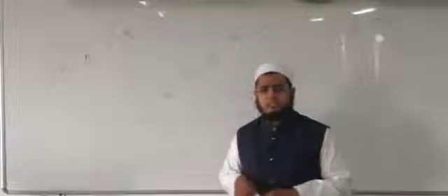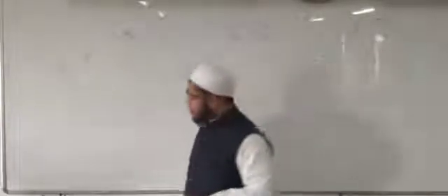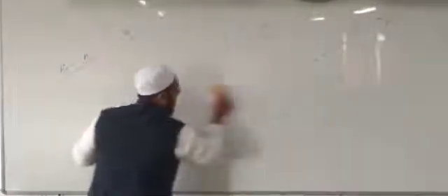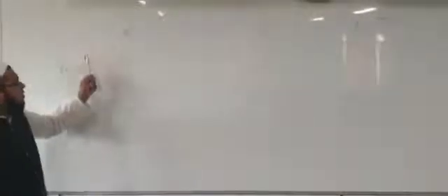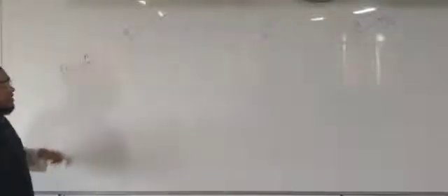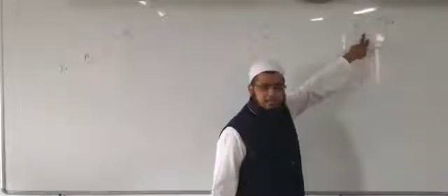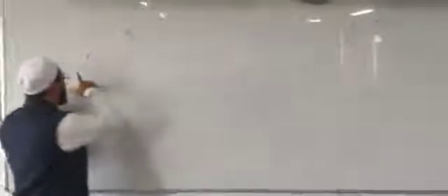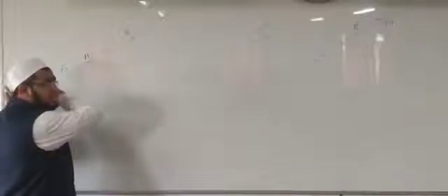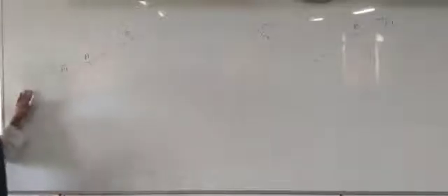There is another type, the sliding vector. In a sliding vector, the vector quantity can slide along a line. Force is a sliding vector, meaning this force F1 acting at A can change its position to B with the same magnitude and direction, and the effect is not changing. In this case, this force F can slide along the imaginary line, that is the line of action.